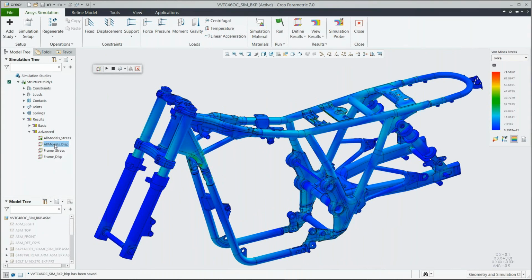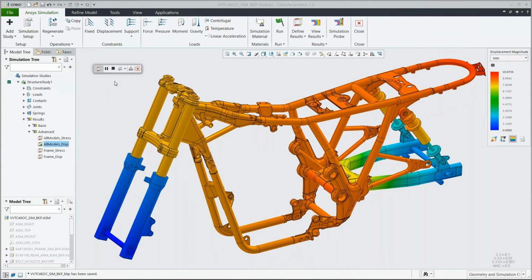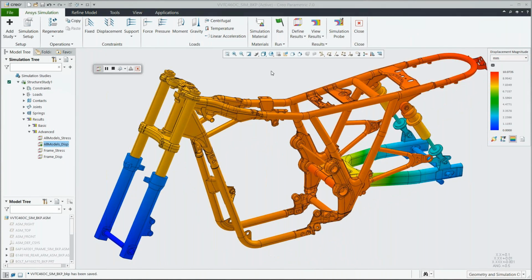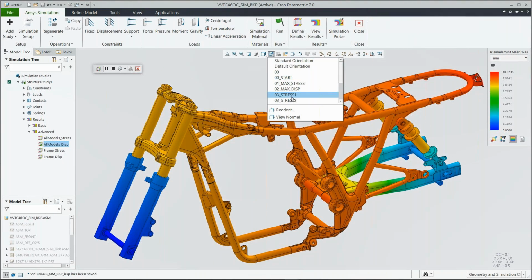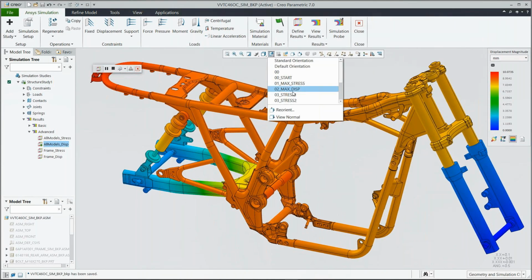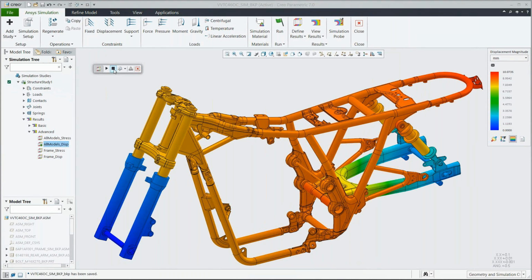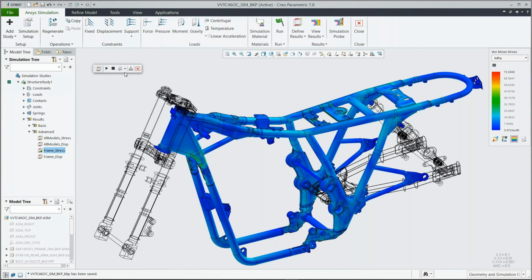the critical components that I'm interested in. I'm able to use those joints that I mentioned here, and maybe even spring idealizations to mimic that suspension in there. At the same time, I'm able to use the ANSYS solver, and it's just Creo Parametric right now. Instead of that, you go to ANSYS simulation, set up your materials, boundary conditions, etc. Look at the mesh, refine the mesh if you would like, apply these joints and contacts, and then run the analysis, and you're able to review the results here as we speak.